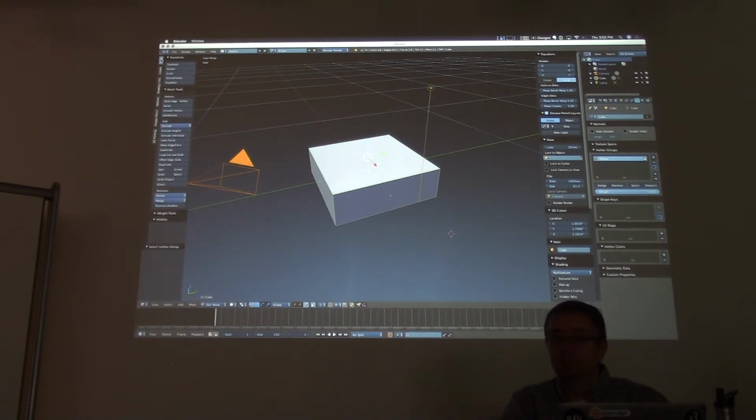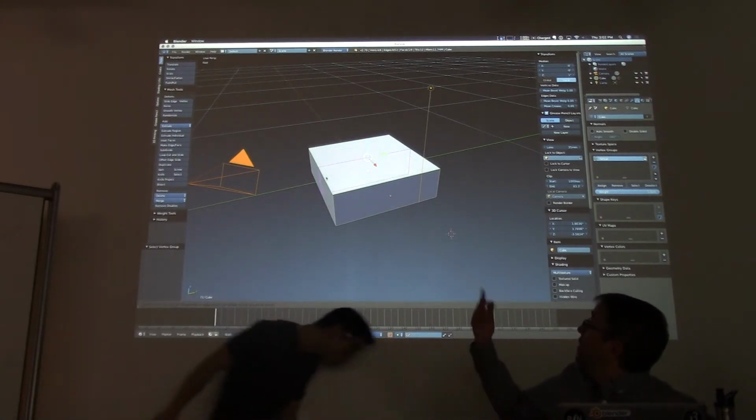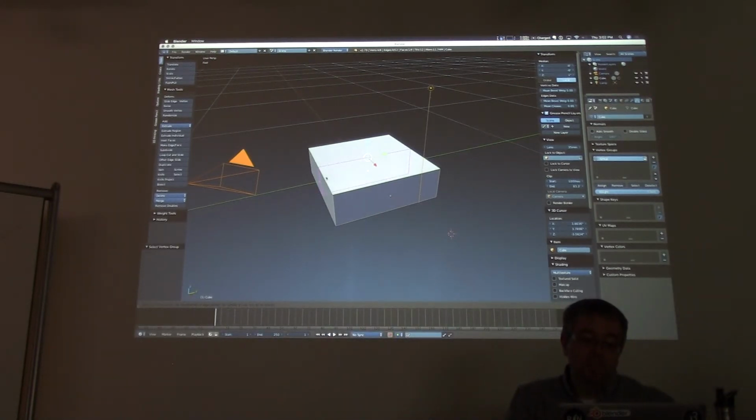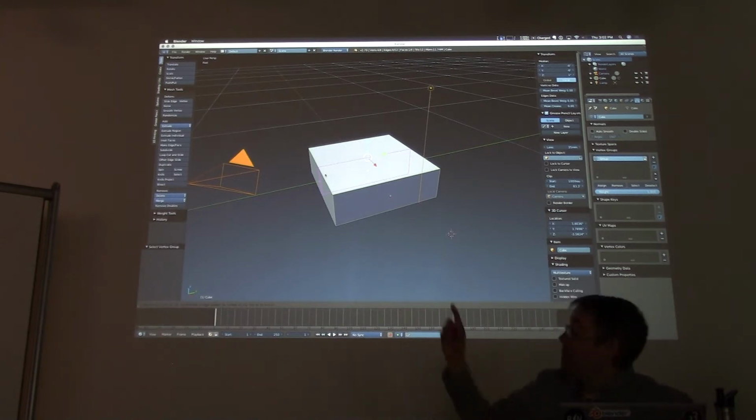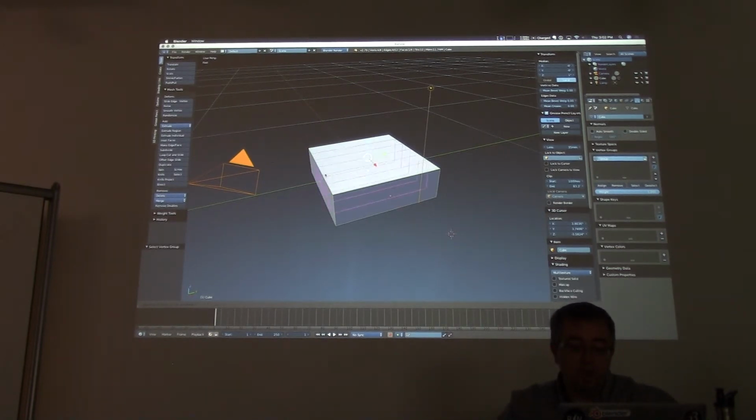But Tools should be up. I'm going to hit Loop, Cut, and Slide. I'm going to pick one of my 3 directions with a pink rectangle, although I only want ones that go this way or this way. I don't want ones that go this way. So I pick a pink triangle, I hold my mouse there, and I roll my mouse wheel until I get 30 cuts.